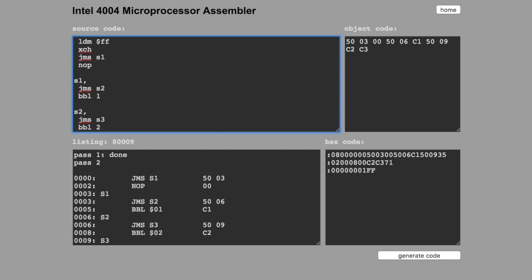And specify the register. Let's take register 1. So we'll exchange the value in register 1 with the value in the accumulator, and the accumulator will put it in register 1. After the jump to subroutine, we can do the exchange again, and we'll restore the original accumulator value.